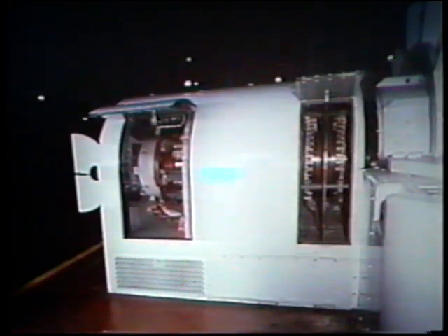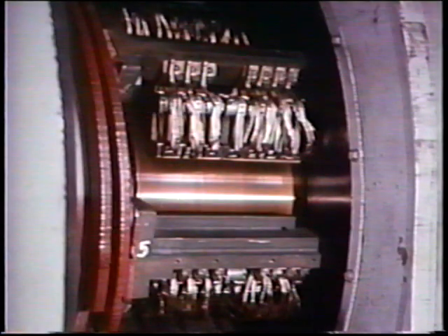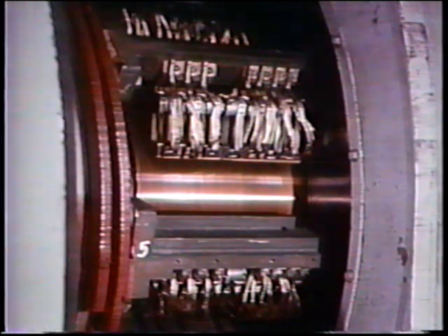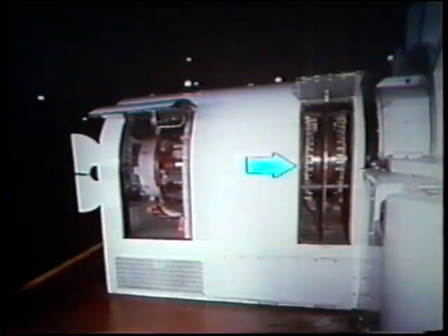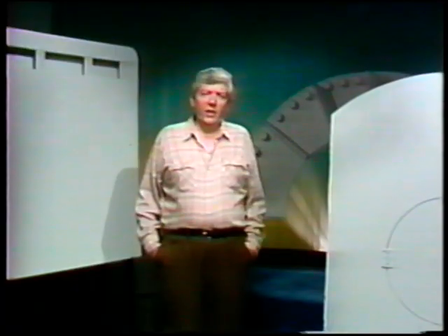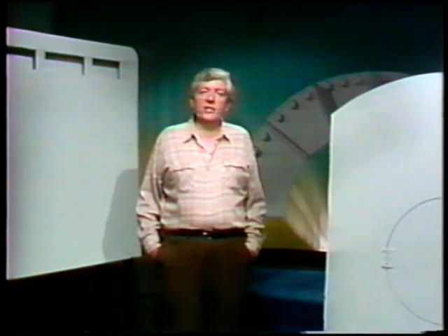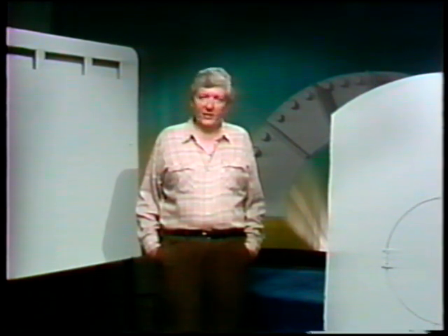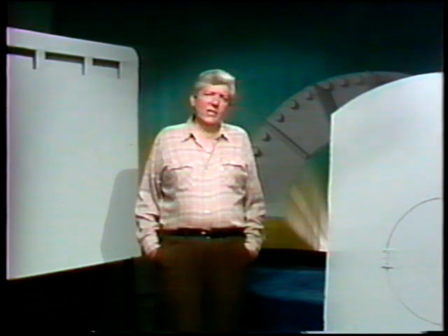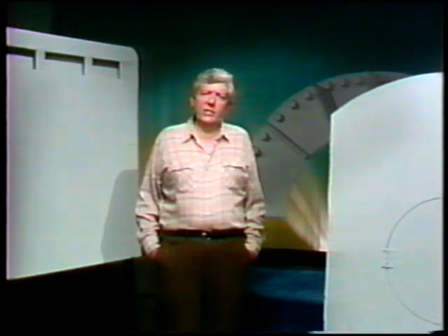Its exciter is a shaft-driven DC generator. A set of brushes collects the exciter's output from its commutator. Then the output goes from these brushes to a second set of brushes that ride against slip rings. These slip rings are attached to the windings of the AC generator's rotating field. Current flow from the exciter through the field windings creates the AC generator's magnetic field. In this case, the exciter is a separately excited DC generator.